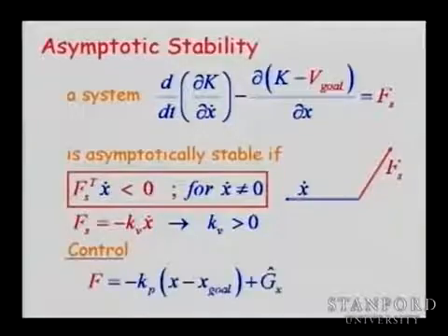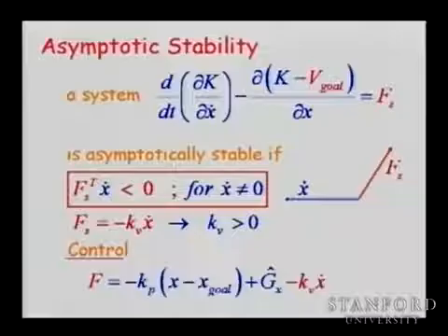You have your control. So this is my estimate of the gravity, to remove the gravity. And this is the proportional term in x. Directly, you take the proportional term, and you have stability here. And when you put this additional damping, you have asymptotic stability. All right?